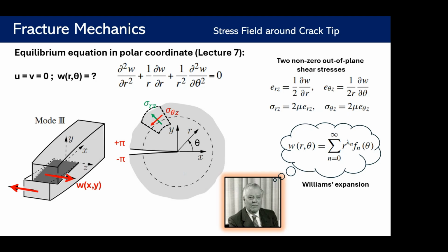We are not focusing on the length of the fracture right now. We are so close to the crack tip. We are just focusing on the stress field very close to the crack tip, and we ignore the effect of the length here. R is just the distance of a point to the crack tip. I mean, we want to find the stress at a distance R, at the specific point R and theta. Any questions?